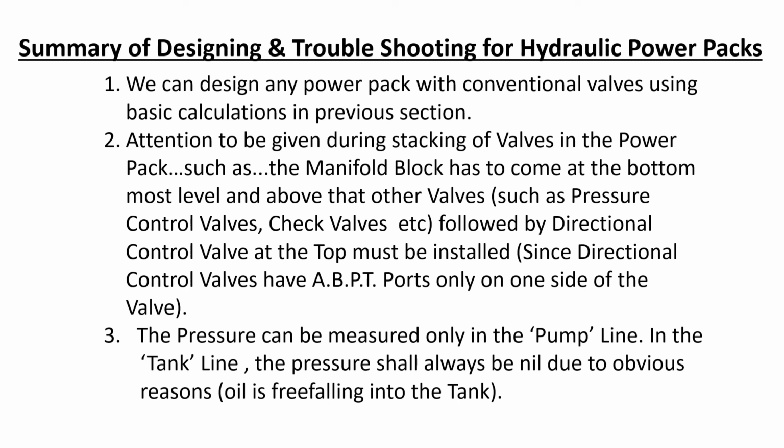So this is a summary we have given for designing and troubleshooting a hydraulic power pack. We can design any power pack with conventional valves using the basic calculation in the previous section. Attention must be given during stacking of valves in a power pack: the manifold block has to come at the bottommost level, and above that other valves such as pressure control and check valves would be assembled, followed by the direction control valve.